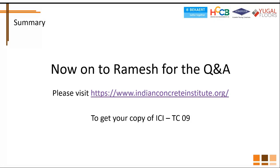Yeah, so basically, a building slab is a suspended slab which has beams, columns, all these elements which are essentially pin supports, and you have higher bending moments in those elements. But as Piyush already mentioned, and I also mentioned in my presentation, a grade slab or an industrial slab is resting on soil, a sort of set of springs. That is the main difference in terms of structural performance. But also there is a factor that one must note: for industrial slabs, the loads are quite heavy. The nature of loading, the machines and equipment moving on it, is quite heavy compared to what you get in suspended slabs. So please don't be fooled by the comparison that I could give a 150 thick roof slab, so I can give the same 150 thick grade slab. Not really, because it depends a lot on the magnitude of loads.